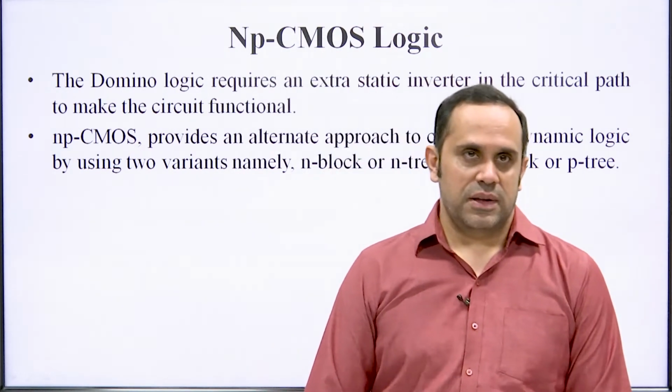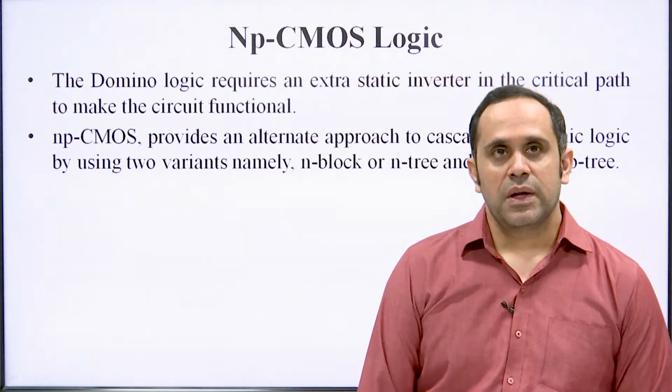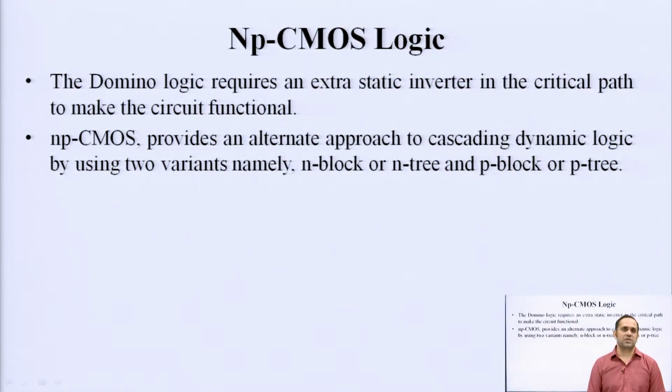Before we move forward, there is one thing I want to discuss. Whatever logic design scheme we use, whatever methodology we use, there is something which is common to every design. In every CMOS logic design, the C in CMOS stands for complementary. The two building blocks are your N type MOSFET and a P type MOSFET. Largely we focus on N channel MOSFET because electrons tend to have more mobility as compared with holes. So, N channel devices tend to attract more attention as compared with P channel devices.